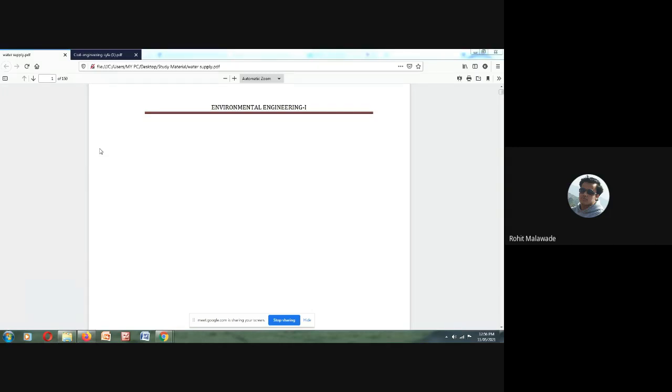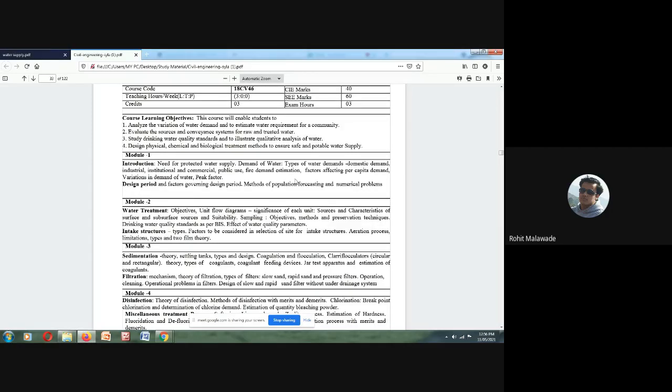What are the factors that are going to affect the water demand? Rainfall, climatic variations, size of the city, living standards of the city, water losses, population, pressure in the water supply line. Population, yes, and living standard of the people. All these will be necessary. Then we have seen population, fire demand, the different formulas, and the factors affecting the variation in demand.